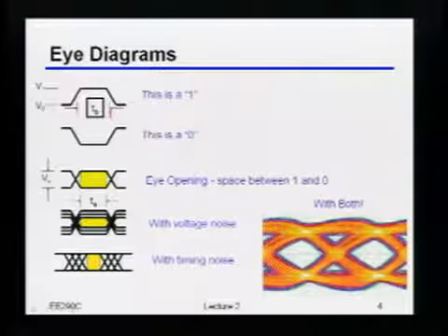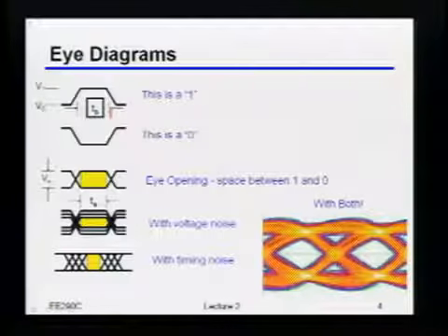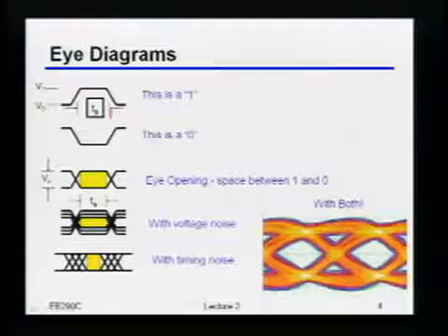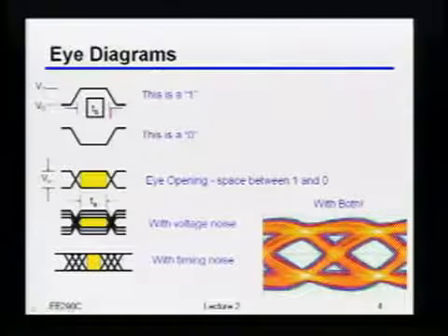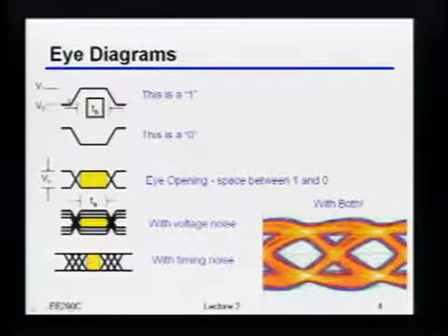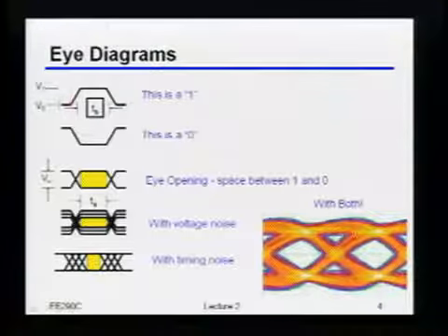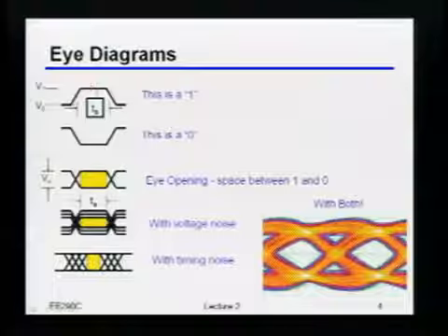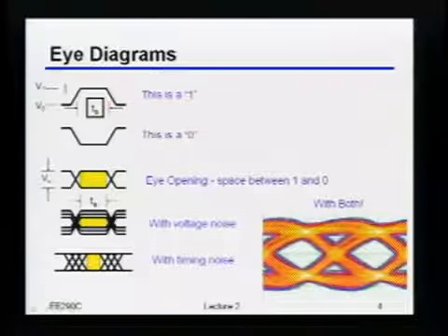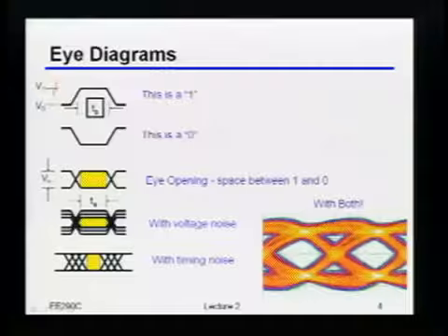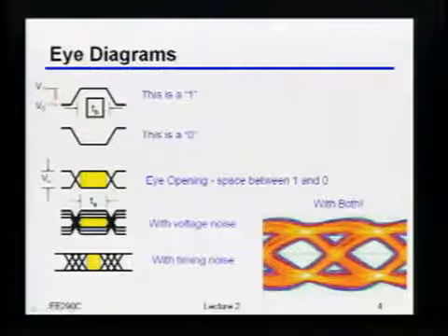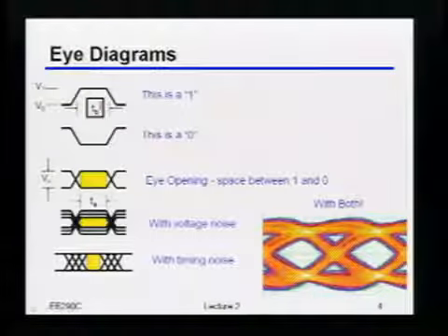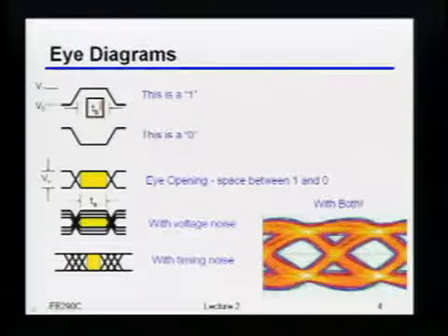So what an eye diagram really is, is this: if I take whatever voltage signal I'm either transmitting or receiving, in this particular example, and for most of this class, we're going to be focusing on these binary types of things, right? So there's just 2 levels there, okay? If I send some low level and some high level, and there's maybe some transition time, what I can do is characterize how much space there is between the low level and the high level, and how much time I have to correctly capture that particular bit, okay?